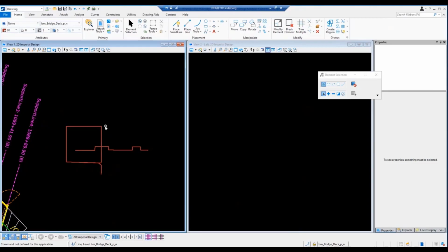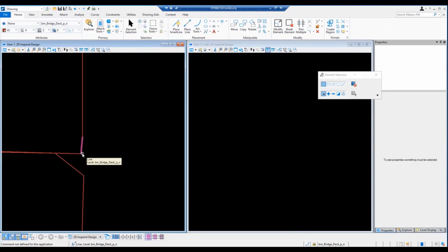The key being that if you then drew a path, it was just a square wave function where it was 10 inches tall wherever you needed an interior post. You would select this point as your point control. You want to tie that to a vertical alignment, that everywhere it was here, it would be 0. And everywhere that it was here, it would be 10 inches tall. And I think you would have to put that right along where this point would connect in to your bridge deck.